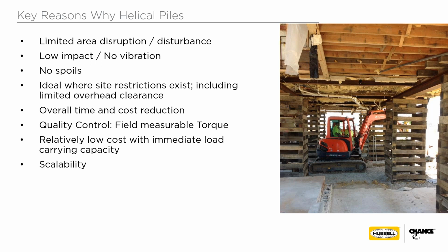They're perfect and great. They're good suggestions or solutions where you have site restrictions, and that could be anything. Building lot sites, underneath structures, like you see in the photograph. Quality control by measuring torque is a great attribute of helical anchors and piles. Relatively low cost. They can be loaded immediately, and we say they're scalable, simply meaning that, as you'll see coming